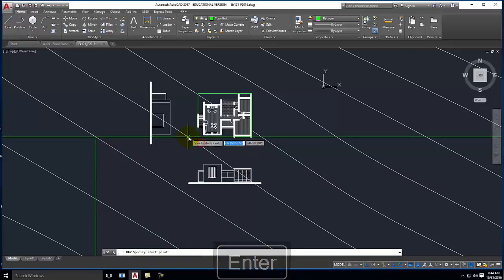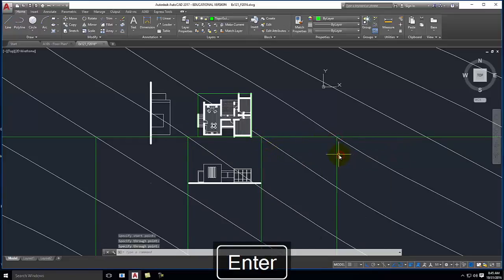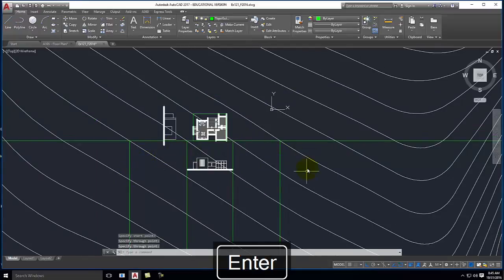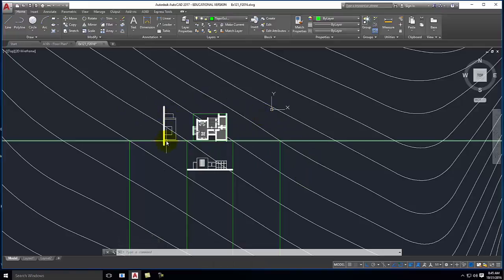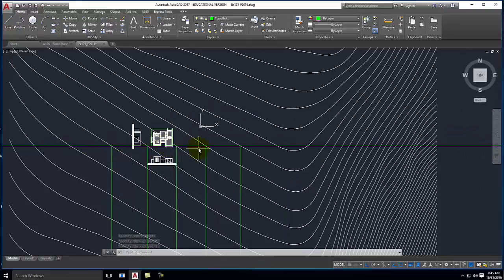I'm going to repeat my ray and go from right there. I'll repeat it and go from right there. Okay? Minimum I need is these, because as I look in the rest of my elevations, those cover all of the topo lines that I'm going to cross. I could do one extra just to make sure I had more than enough contour. Okay? So, again, it's everywhere that it crosses those lines.